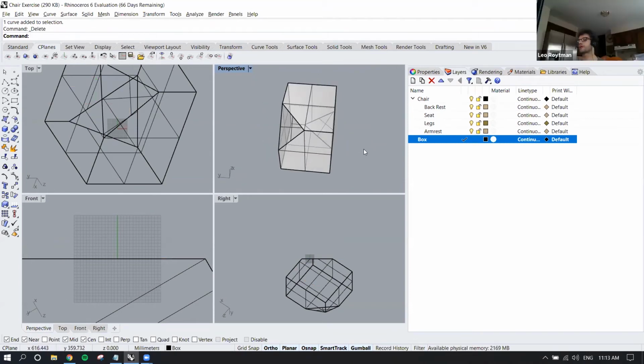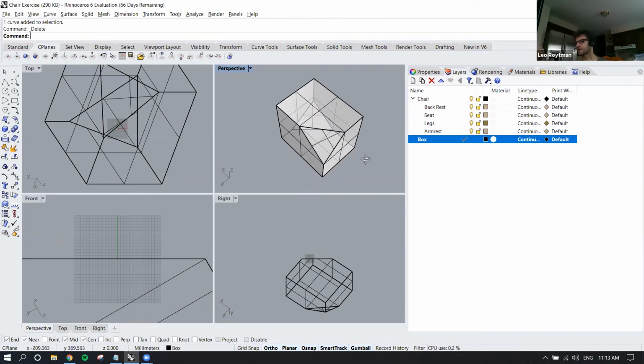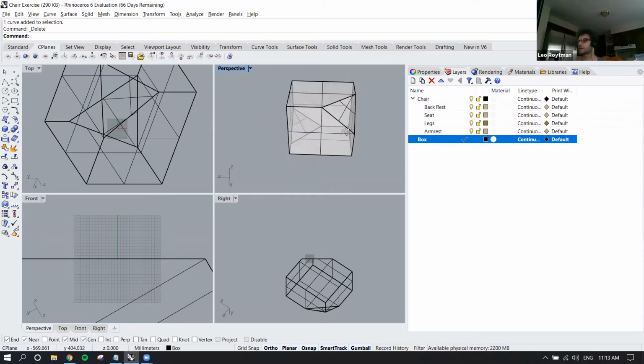And for example, if Eric wants to perform a Boolean operation, for example, making a deep cut in his object, he should draw a rectangle on this construction plane and then extrude it inside and then perform a Boolean operation. And that's the benefit of using construction planes.